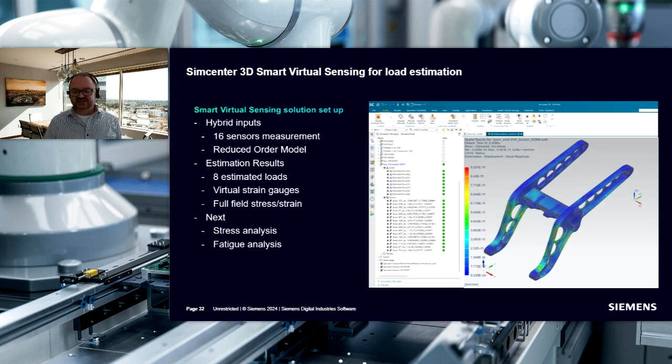What we did there is we first calculated the strains that we used for the back calculation already with the multi-body simulation tool, where we already knew the real durability results which come from the multi-body based load prediction. But we now did it using this new tool, where we calculated from multi-body the strains at, I think, 16 different positions here,